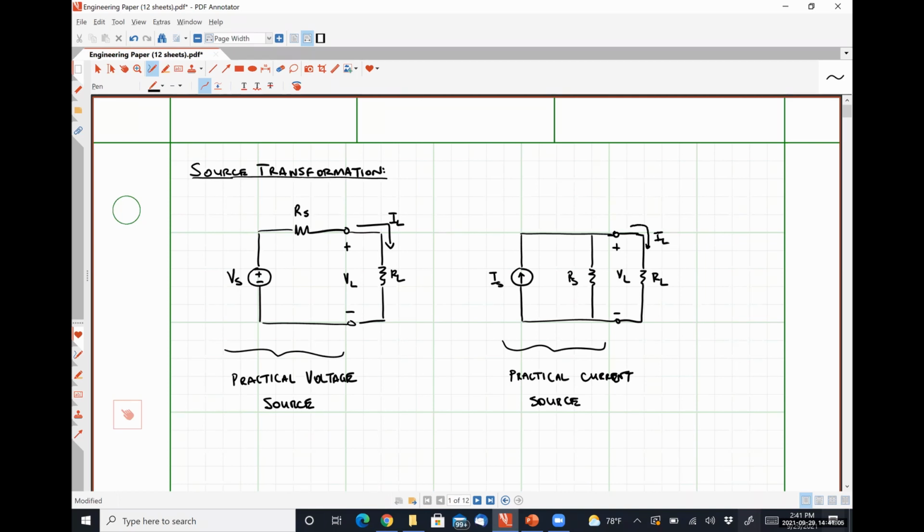We had a source and we connected it to either a single resistor or a bunch of resistors in some potential configuration. And we said that those resistor networks are electrically equivalent if the same voltage drop appeared across the terminals of the network and the same current flowed into the network. We have the exact same situation here, but we're trying to make the source side of things electrically equivalent.